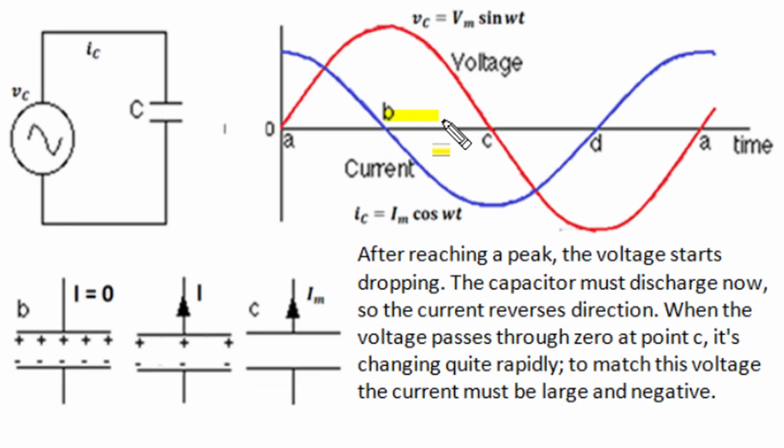In the next quarter, at the beginning, the capacitor is fully charged and there is no charging current, but just after that the capacitor starts discharging and the discharge current direction gets changed, and by that discharge current the charge and voltage across the capacitor decrease. When voltage decreases at a slower rate the discharge current has smaller magnitude, and when voltage decreases at a faster rate the discharge current attains peak magnitude, and at position C the capacitor gets fully discharged and the circuit gets maximum value of discharge current.